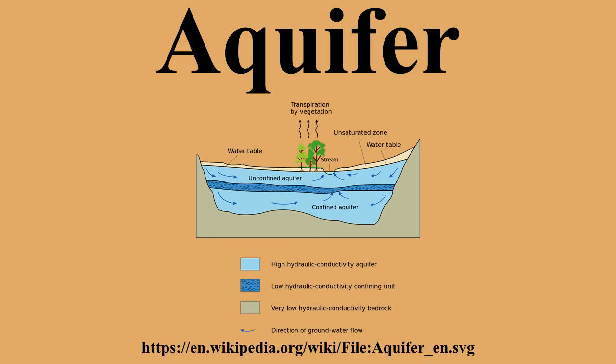If the aquifer is confined by low permeability layers, the reduced water pressure in the sand and gravel causes slow drainage of water from the adjoining confining layers. If these confining layers are composed of compressible silt or clay, the loss of water to the aquifer reduces the water pressure in the confining layer, causing it to compress from the weight of overlying geologic materials.